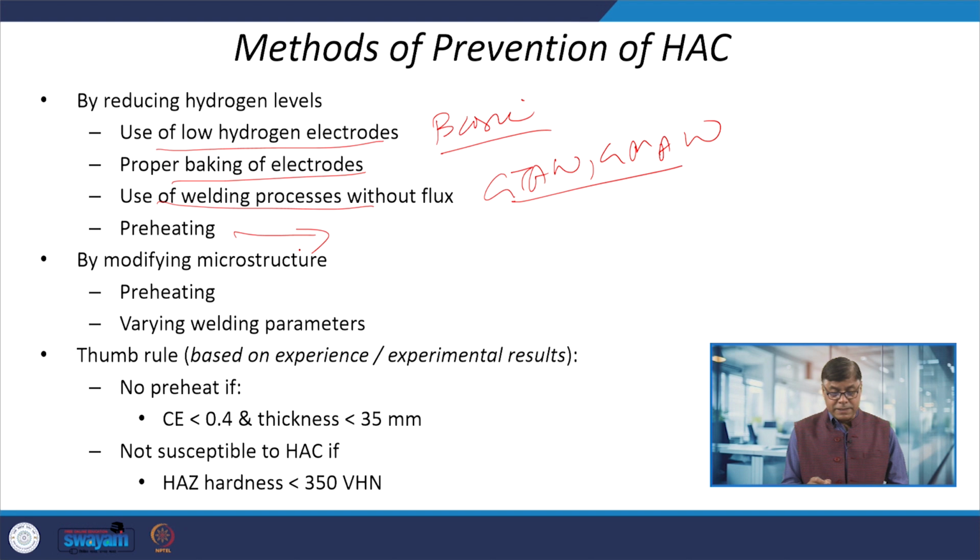The advantage is that our cooling rates are reduced with the preheat. High temperature retention time is increased, so that will give enough time for the hydrogen to escape during the solidification and during the cooling. Another thing is to avoid the hard and brittle phases. So this first approach deals with reducing the hydrogen level.